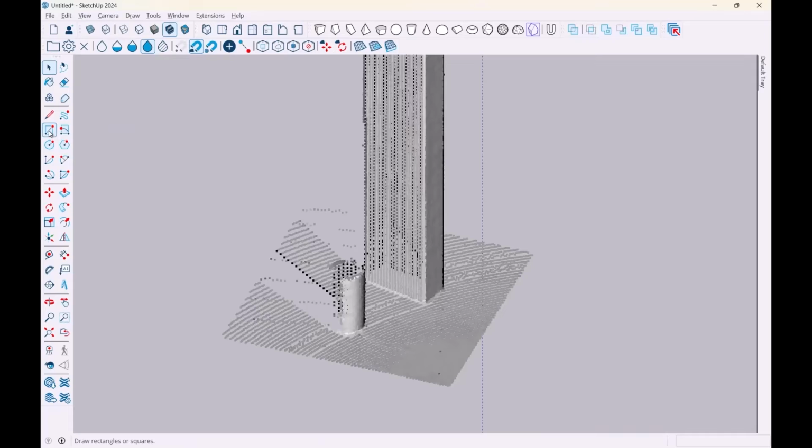Okay, let's take a look first at drawing on the model. You can draw right on the model by simply using any of the SketchUp tools right here, and then you can just click on the model. The very important bit here is enshrined in these three toolbar buttons on the Scan Essentials toolbar, where you basically can choose between picking a point cloud point or a SketchUp entity. If you have SketchUp entity, then of course it'll look behind there and just draw in the SketchUp space. And then of course point cloud is when you draw on your point cloud.